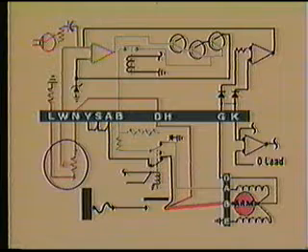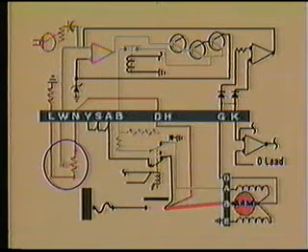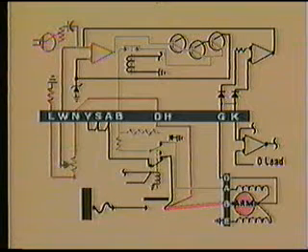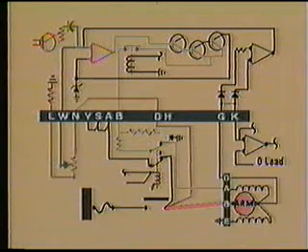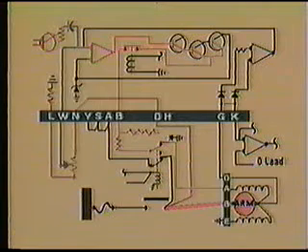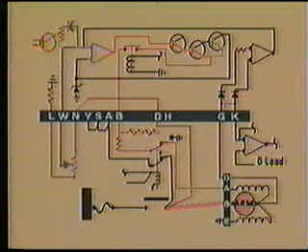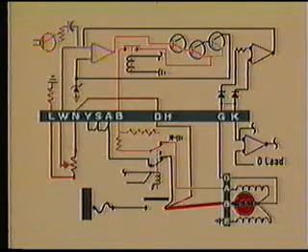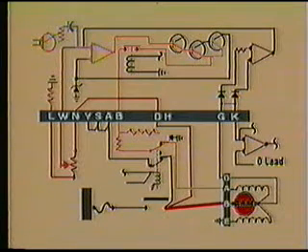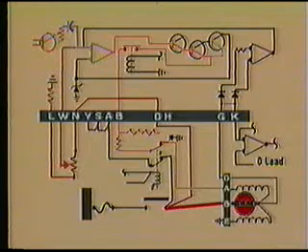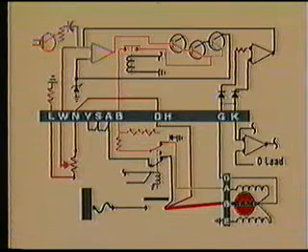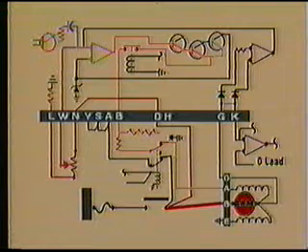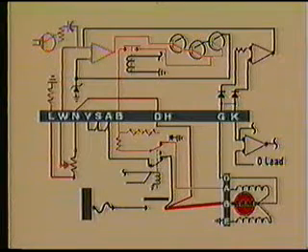We can adjust the output voltage at which this equilibrium is reached through means of the potentiometer. If the generator voltage decreases, say because of a greater load being applied, more of the oscillator signal will act on the amplifier, which will cause its output to increase, and thereby increase the A-lead signal, which increases the output voltage of the generator. Because all of the components are solid state, these types of adjustments and reactions can take place instantly.